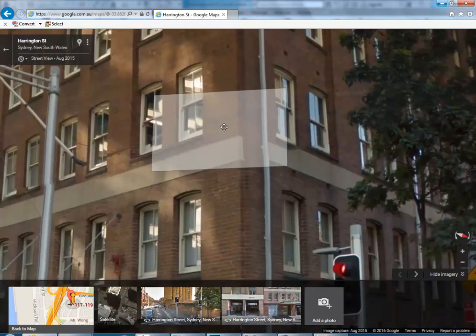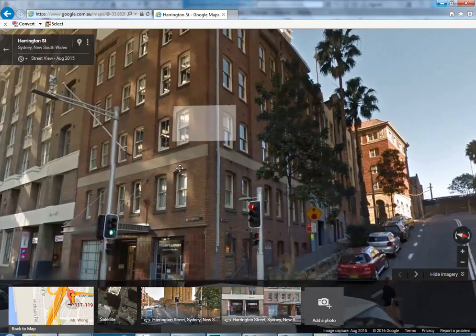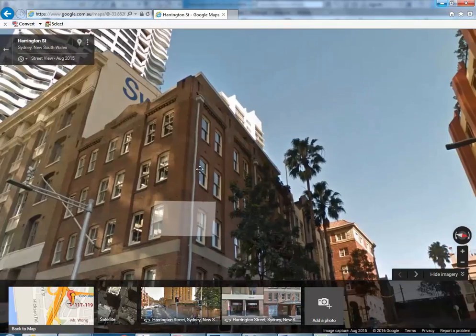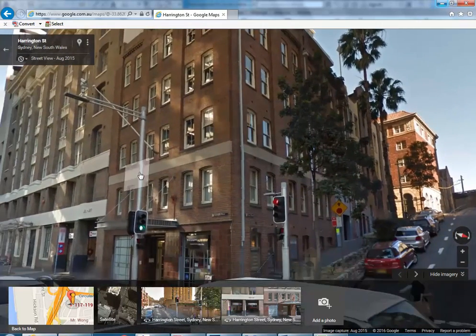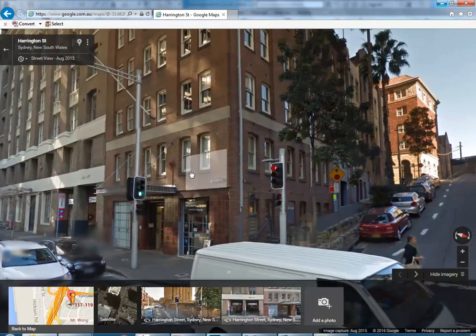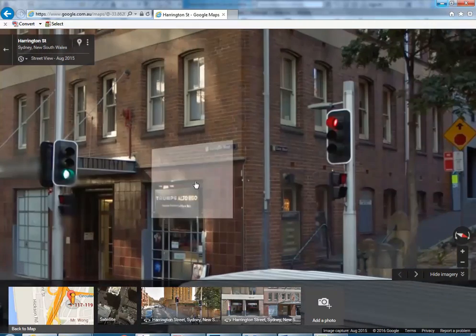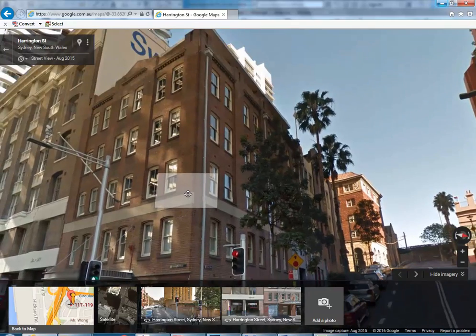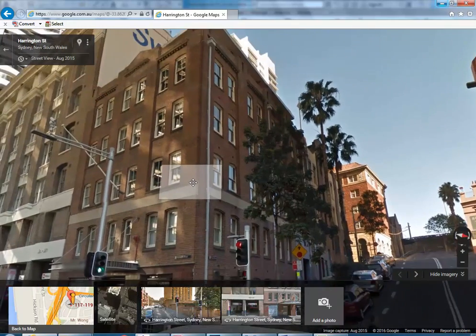You do have these bays with piers either side, which are set back, and so we should really use separate walls for those. So the walls here from the ground floor really can only go as high as the second floor, and then we can do a new set of walls for the levels above that.